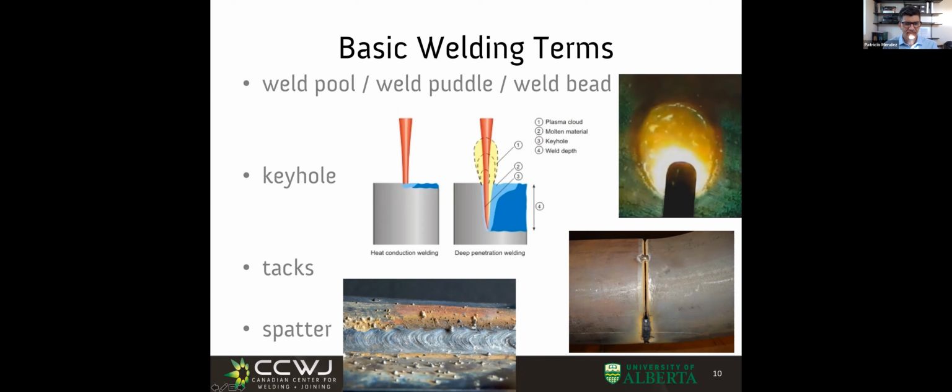We mentioned tacks. Here the tacks are here. Here we have some spatter, typically it's bad. But again, if you take a look at the Lincoln Procedure Handbook, spatter is never pretty, but sometimes it disqualifies your weld, and sometimes it means nothing.